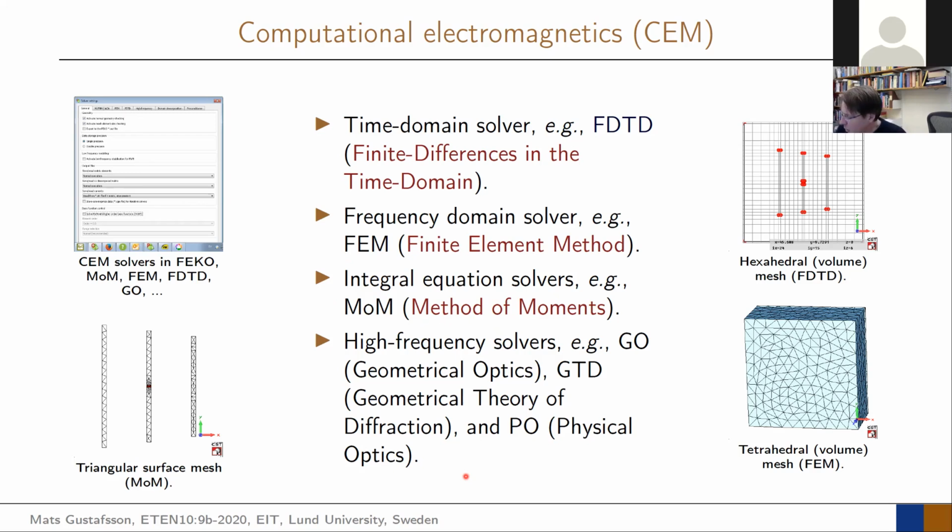What's happening in basically all of these ones is that you take your structure and, in some way, discretize it to a finite structure. In these cases with these dipoles that we see down here, you can see a lot of small triangles. In reality, you have your dipole, like a piece of metal that sits here. You approximate it so that the currents can only change over a certain scale. If you have very few triangles, it's a coarse sample, and you can maybe not describe the currents you should have there. If you put in more of these triangles, you get a finer sampling of this current.